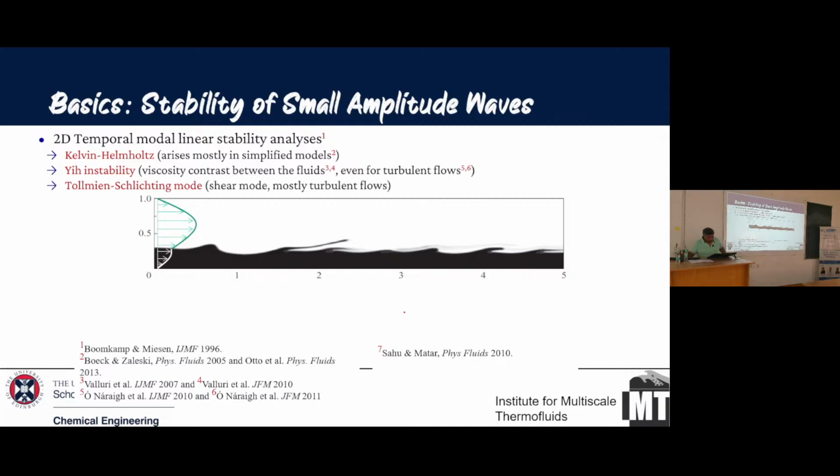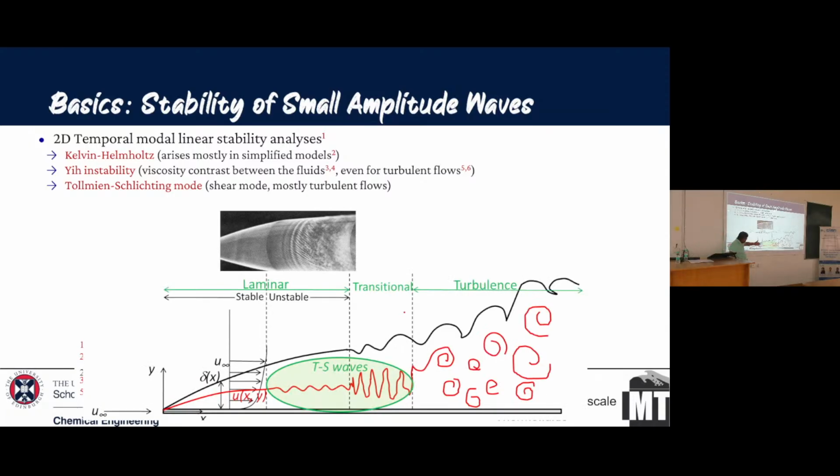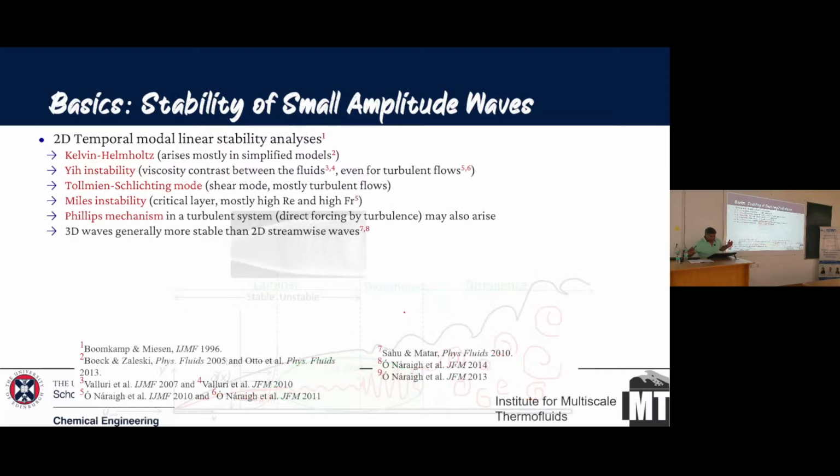The other thing, obviously, we talked about is the Tollmien-Schlichting mode, which is internal. These are Tollmien-Schlichting waves which disturb the boundary layer. I don't need to go too much into that. The other thing is the different ways in which instabilities can kick off. If you have a two-layer system, with gas and liquid flowing through, sometimes you have another instability which is kicking off from the wall.